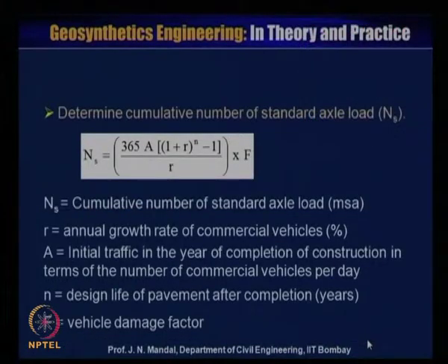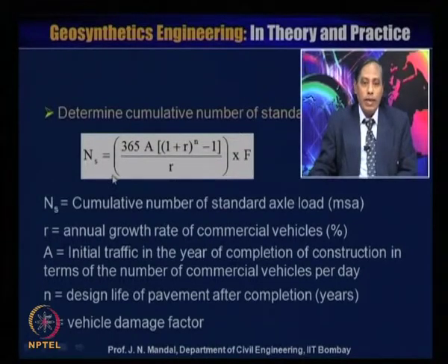Now determine the cumulative number of standard axle loads, NS. You have to calculate the standard axle load with this equation: NS is equal to 365A into (1 plus R) to the power N minus 1, divided by R, into F, where NS is the cumulative number of standard axle loads, that is MSA.